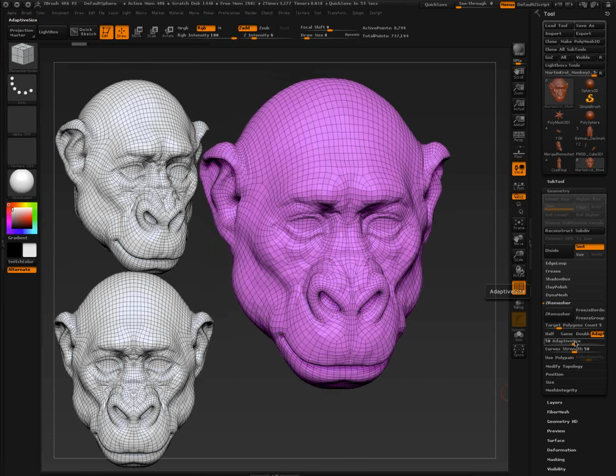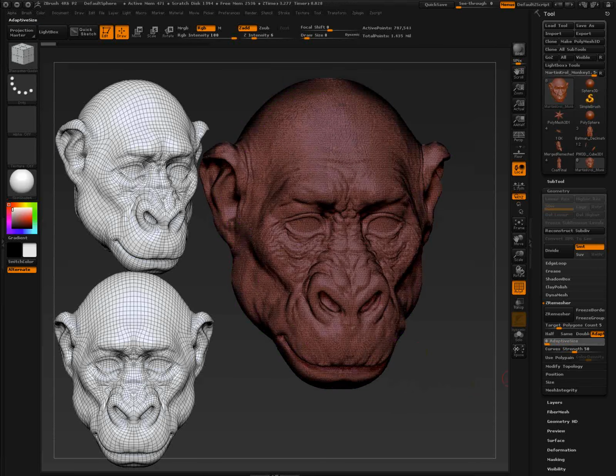So at 50, it's telling ZBrush, hey, I'm going to let you make polygons 4 times smaller than the biggest polygon. You can have a longer polygon, which means more of a rectangle polygon. That's what that slider is doing. So if I take this same slider and knock it all the way down to 0, what I'm telling it to do is to try and make the polygons all equal size. As best as you can, try to make them all squared everywhere that you can, and don't allow as many rectangles. Keep them all relatively the same size.